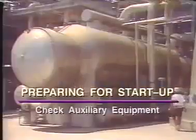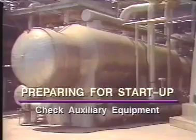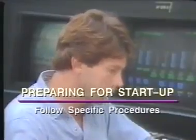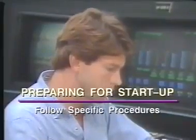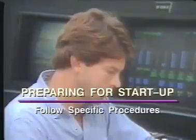Before starting the tower, make sure that all auxiliary equipment like reboilers and condensers are ready for operation. Also, make sure that any water that might have settled in low points has been drained out. The procedures for the actual tower startup will vary from column to column. You should always follow the guidelines for your particular tower.